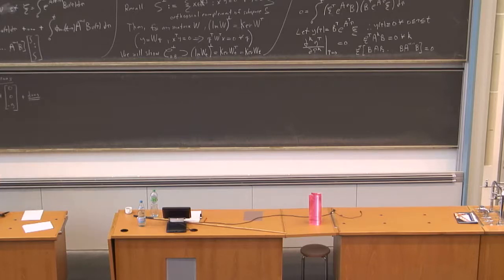to the angular rates of the vehicle in its own frame. And I basically have this kinematic relationship: R dot, the rate of change of this orientation matrix, is the orientation matrix relating the rates. Omega sub x, omega sub y, and omega sub z are the rates in the vehicle frame.